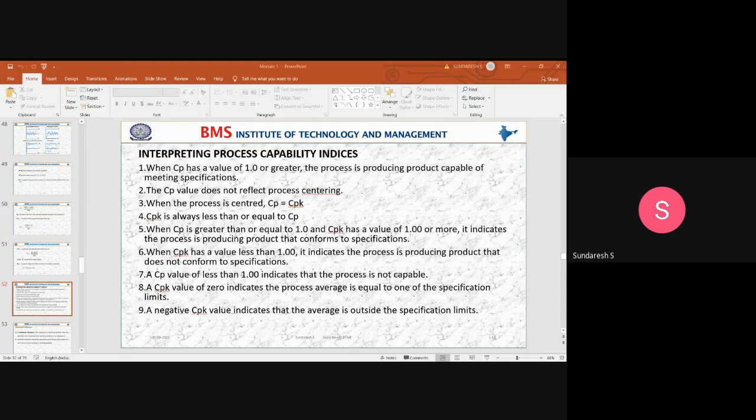Right. Based upon that, you get a unilateral tolerance or a bilateral tolerance. If the variation is permitted only on one side, whether on the positive side or on the negative side, it constitutes a unilateral tolerance. And if the variation is permitted on either side, positive or negative, then that is called a bilateral tolerance. This is what you might have studied in your engineering metrology, and you know how to calculate these tolerances, and based upon the tolerances, how we can define a fit. So clearance fit, interference fit, or transition fit, all those things, right?